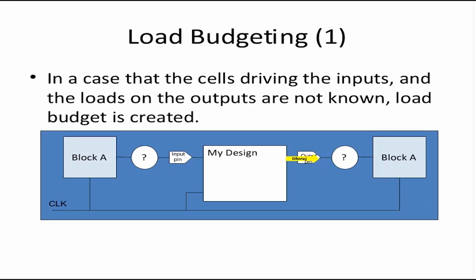You apply a load here, which is typically the maximum load your combinational cell can drive. So for example, you have three cells, X1, X2, X4. Choose what maximum load your X4 can drive and set that value using set load here. What DC will do now is it will know that you are driving this much load, and it will always choose X4, the drive strength 4 of the register that is driving the output. So you are on the safe side.